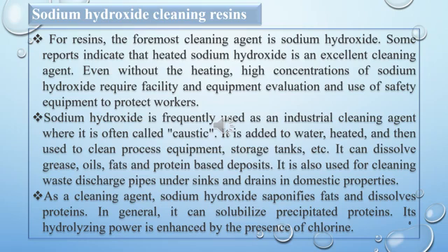The next point is, as a cleaning agent, sodium hydroxide saponifies fats and dissolves proteins. In general, it solubilizes precipitated proteins. Its hydrolyzing power is enhanced by the presence of chlorine.